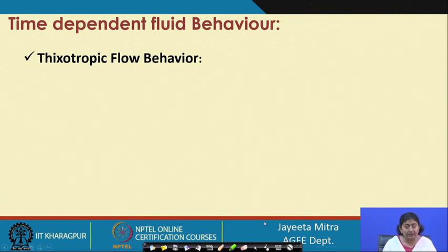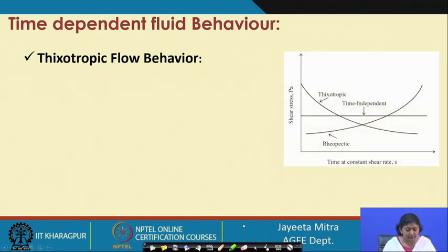So, then we will consider the fluids which are time dependent. Till now we have considered the behavior which are time independent. Their viscosity will change with the rate of shear, but does not change with time. But now we will consider certain non-Newtonian fluids which will also show different rheological behavior with time if the shear rate is constant. Okay. So, the first one that we will consider is thixotropic flow behavior.